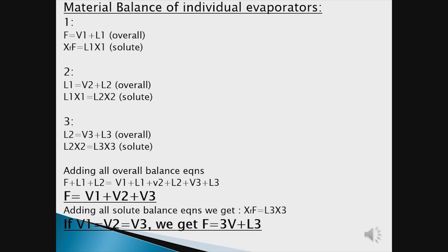And coming to the solute material balance for the first evaporator, we can see that XF into F is equal to L1 into X1, where XF is the composition of the feed, and L1 is the flow rate of the thick liquor. We are not considering V1 because it is in the vapor state.